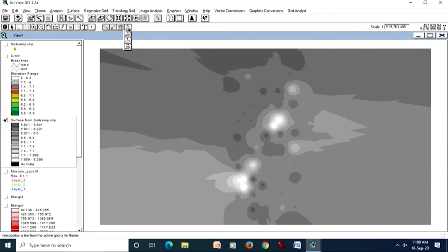I will deliberately draw a polygon which is not really rectangular or square in shape, so that I can demonstrate some other interesting thing about GIS capabilities. I have created a polygon which is not really rectangular or square, but remember that a raster can be stored only in two shapes, either square or rectangular. So what would happen in this case?